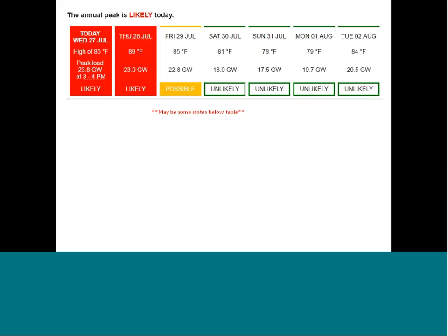The hour is important because they determine which hour is the peak, and they look at what you were doing for capacity in that time. But the hour can move slightly, because other people are taking actions and their predictions aren't always right. So I think last year on that August 12th day, we got the day right. We called it as a likely day. From ISO's data, we predicted it would be from 2 to 3 p.m., and it ended up being from 3 to 4 p.m. So it can move slightly, so starting your load shed a little early and ending it late can be helpful, depending on if it moves.